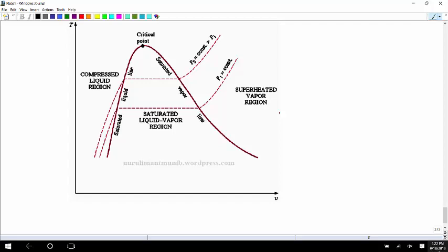But then once you get up to the boiling temperature, now something different starts to happen. So right when you get to the saturated liquid at 212 degrees Fahrenheit, now you still have the fire under it, but if you had a thermometer in that liquid, you would not measure any change in temperature anymore for a long time. Okay, that water gets up to 212 degrees Fahrenheit. And from then on, what's happening is the water is just starting to boil. You're getting the start of the phase change.